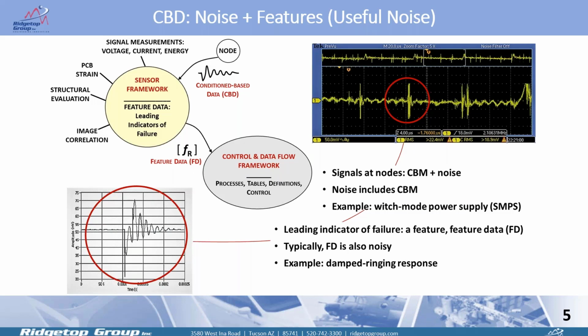Everything can be used, if you really think about it, for prognostics. But you can't look at everything and you can't process everything. So a prognostic engineer has to look at the data, look at the failure mode of interest, look at the tools he has, the sensors he has, the processing firmware he has, and say, okay, this is the feature I'm going to look at.